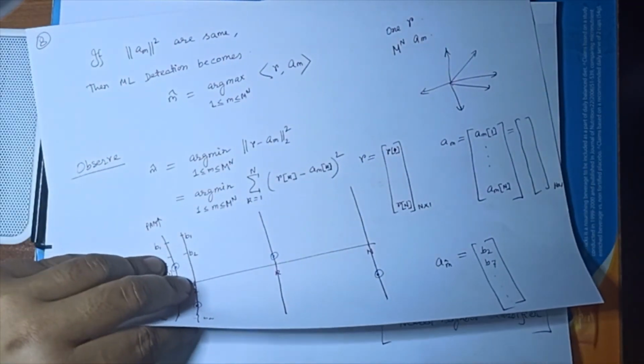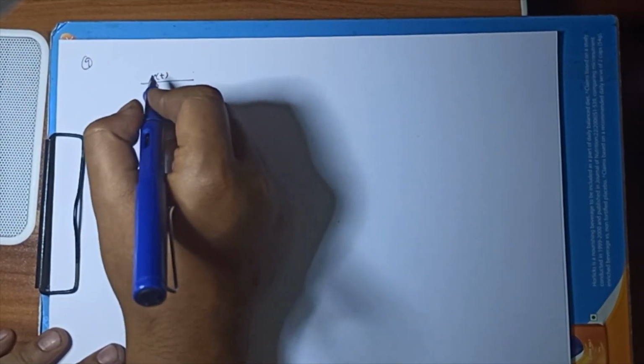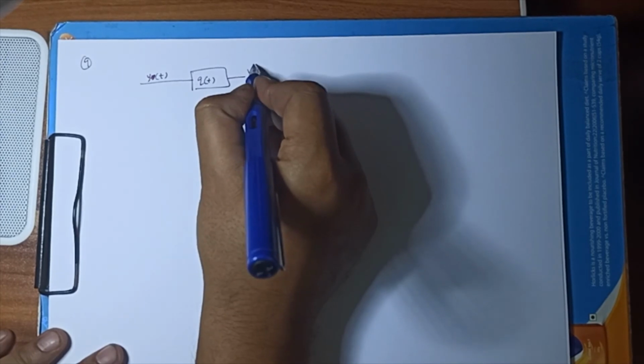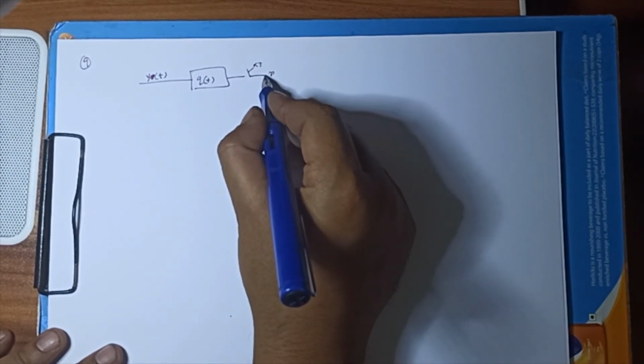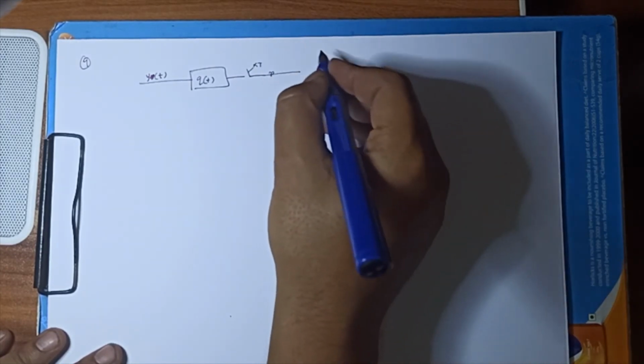So I can show you how the circuit will be. The circuit is basically, for the scalar one, your signal is coming, r(t), you have your y(t) passing through the matched filter, and then you are sampling it. If you sample it, you get basically R. That R you have to threshold. You have all the different B's available, right?